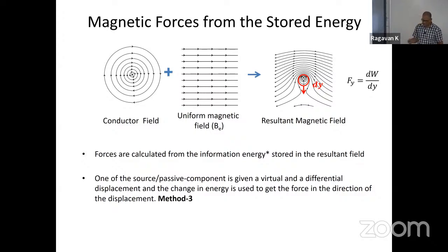If you have an analytical expression for the magnetic field distribution, then you will simply differentiate the energy with respect to, let's say, a rotor movement or the conductor movement. If it's a finite element analysis solution, you assume that the mesh got deformed by a small distance, like all the triangles inside the air gap got stretched by a little displacement. And because of that stretch in all the triangles, what is your new solution for the magnetic fields? You see what the change in energy is and take the differential. Whatever I said is presented in a simplified matrix form by researchers. So it is doable.